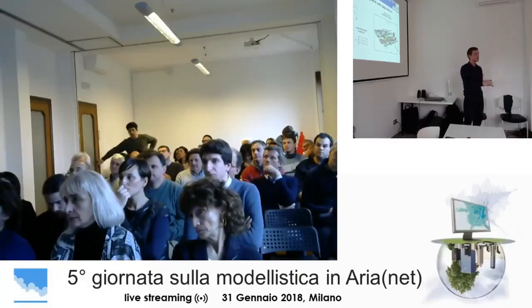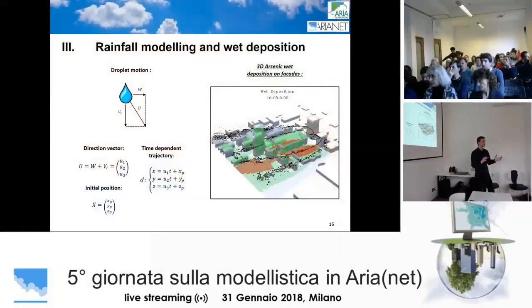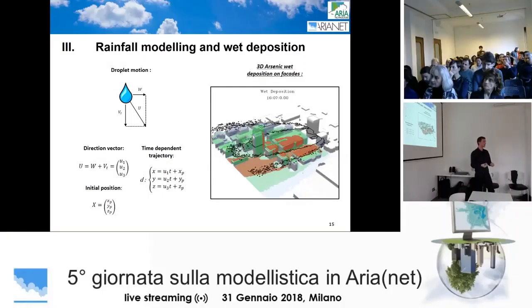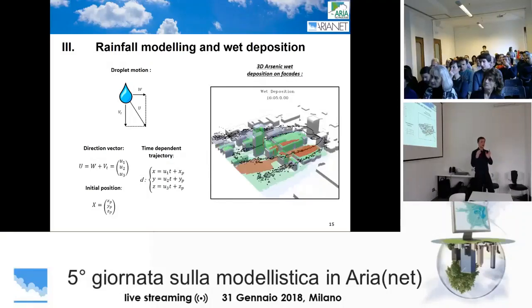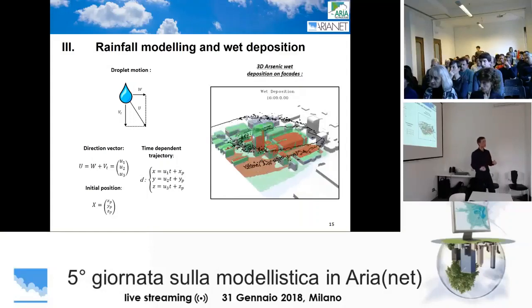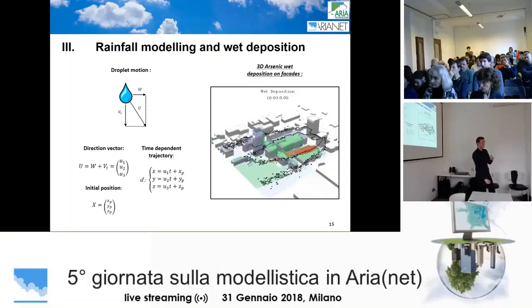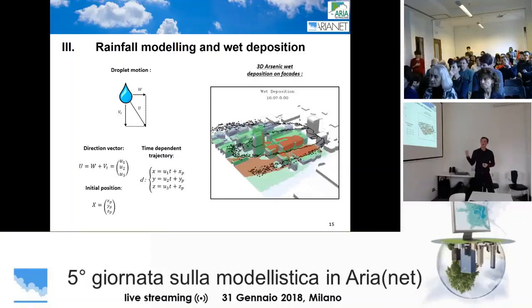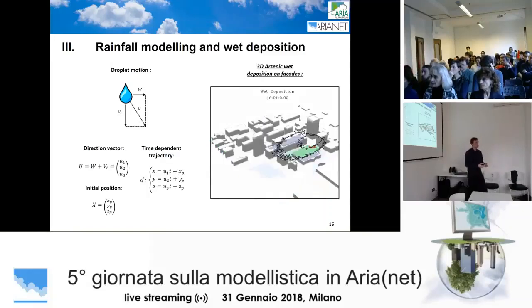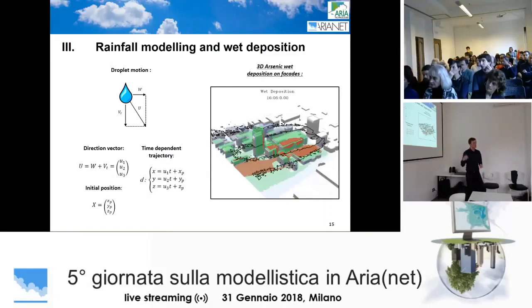So PMSS Microspray is a Lagrangian model. So the plume is represented by a cloud of particles with positions. And each particle carries a mass. So when we have a particle, during a small time step, we compute what is the amount of mass that we remove from the particle to deposit on the ground. And the amount of mass that is taken from the particle follows the decay law that we saw earlier.